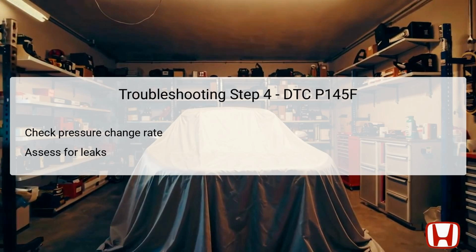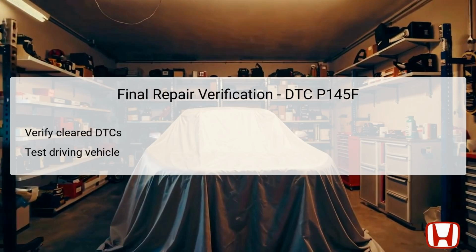Documenting the conditions under which you measured the pressure change will also be beneficial in guiding next steps in the repair process. Upon completing repairs related to the EVAP system, it is imperative to perform a final verification step to ensure that those repairs were successful. First, confirm that any DTCs stored in the PCM have been cleared following the repair work. It's best to utilize the HDS for this process to ensure accuracy.